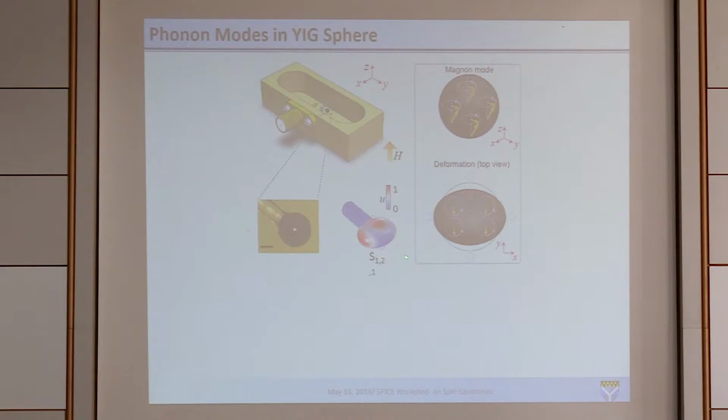And along that direction, you have a 0 displacement over here and a 0 displacement over there. So when you glue your little fiber, you want to make sure you glue at a place that has a minimum mechanical displacement, so you're not spoiling the mechanical Q. And this actually turned out to be a very nice mechanical mode we're looking at.